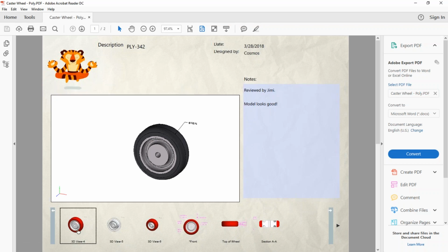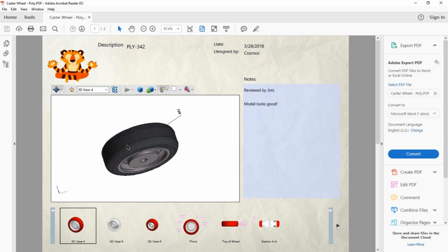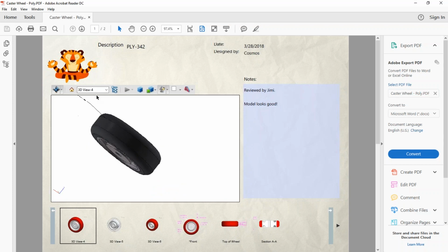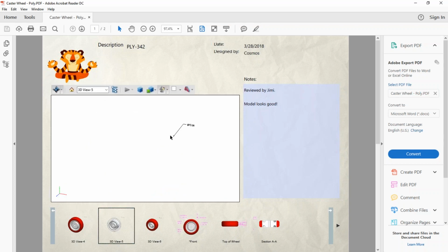You'd see that 3D View 4 is here in the main display, and I can click to drag it, manipulate it, rotate it as required. Some of these things show up as planned, some of them don't. You can see that my transparent view there just ended up showing up completely transparent. No worries, that can be changed in model display sometimes.